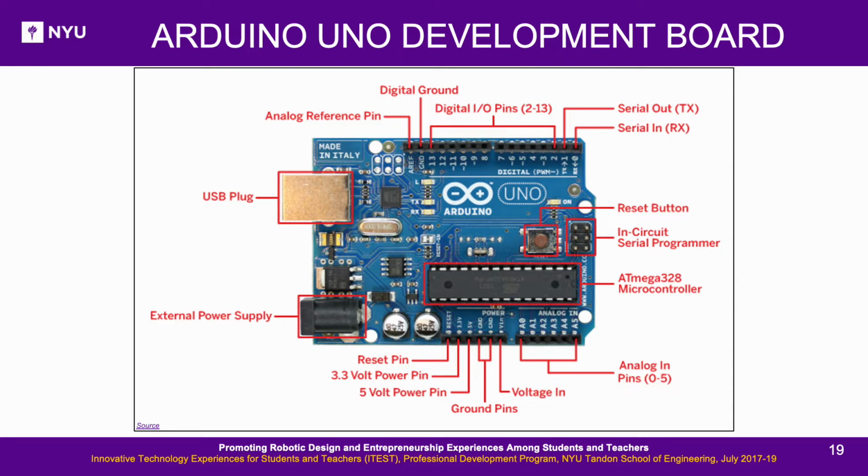TX and RX pins are used for serial communication. The TX LED and RX LED are internally connected to digital pins 0 and 1 to show what way the serial communication is taking place. In addition to the above LEDs, there is also an onboard LED internally connected to digital pin 13. There is also a power-up LED which blinks when the Arduino is powered.